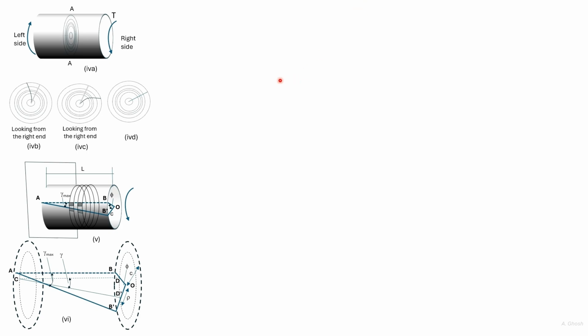Due to this inconsistency, we have to conclude that a straight line after torque has been applied remains straight, which means the angular rotation of the different concentric circles remains the same. Thus, there is no distortion between different parts of a given plane.